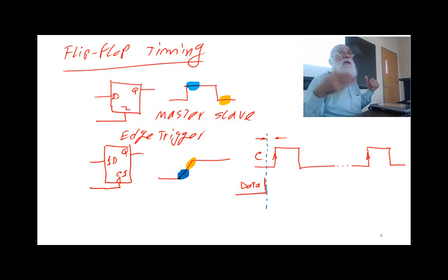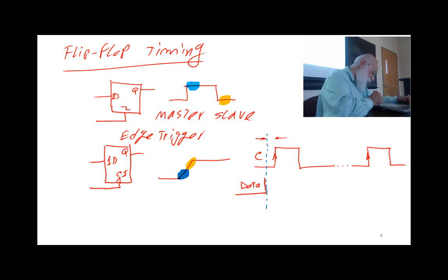I'm not going to go through, actually we never go through all the details of the timing for the D flip-flop, but we just say that if you are operating a flip-flop, you have to follow the setup time. Don't change your data too close to your clock edge. This timing, I'm calling setup time, T setup.